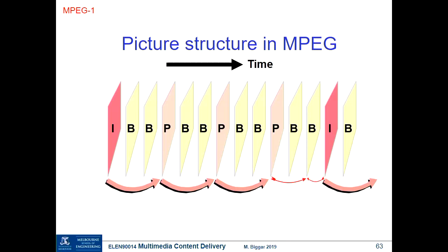So these are effectively just being interpolated using the assistance information from the encoder. Right. So the B pictures are predicted from past I or P and future I or P, the P pictures are predicted only from past I or P, and the I pictures aren't predicted at all.